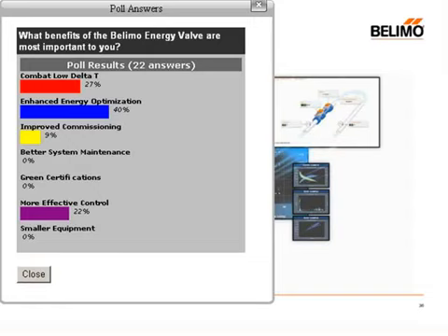Okay, we have another good question here. How are the characteristics of the actuator and the valve integrated to produce one operating characteristic for the combination? This is achieved by the delta T manager algorithm. As we talked about earlier, as I like to use the Apple philosophy, these components are designed together, where the software and the hardware are designed to operate as a validated system. By having control over both the hardware and the software, in this case the delta T manager algorithm and the control valve itself, that's how we control and produce a single characteristic.